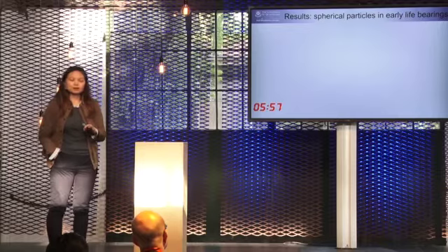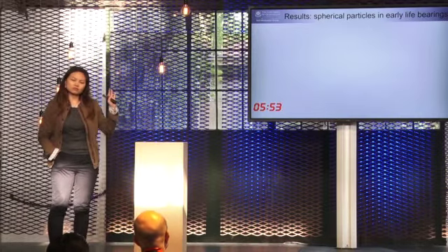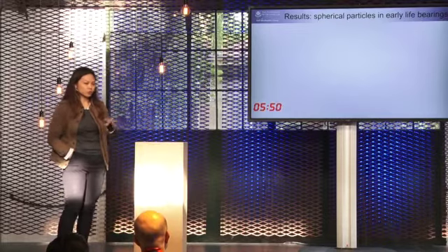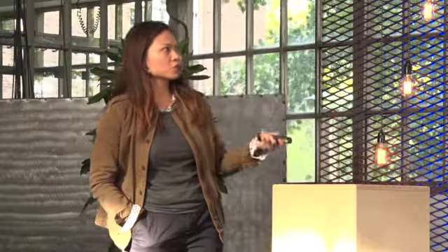Now, there are 7 types of wear particles we found, but there are 2 very interesting types within the different types of bearings. The severe particles we found have different morphology depending on the bearing usage.